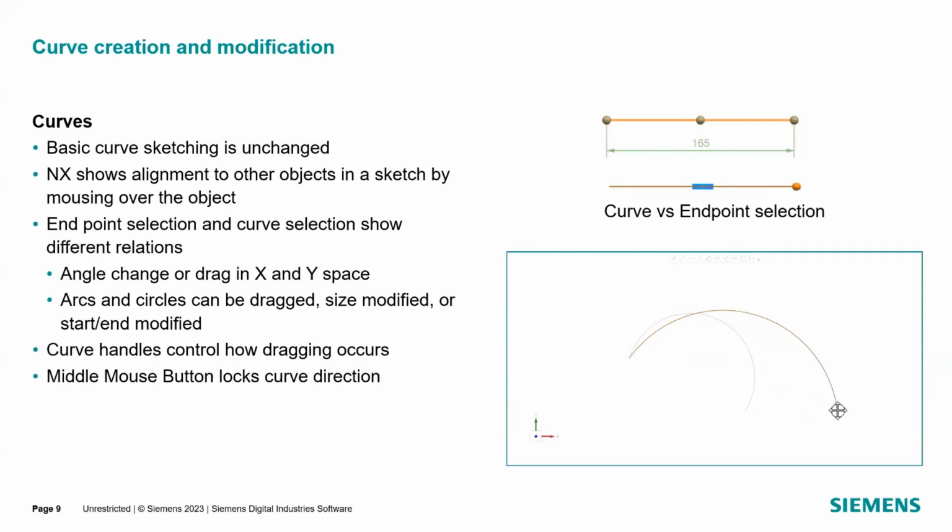When you select those, as we see in this arc, it allows you to do different things, right? If we click on the center, we're moving the center of the arc. If we're picking on the endpoints, we're adjusting the end of the arc or line segment. By selecting on that, you get a little bit different behavior. Those will be some things up front as you start to work in it, understanding how that impacts based upon what you've actually selected.